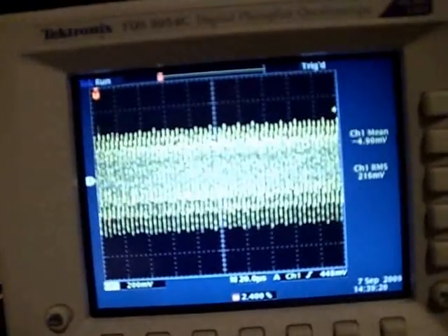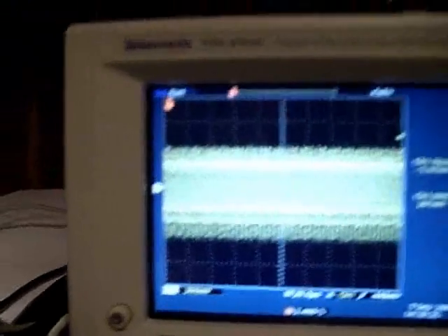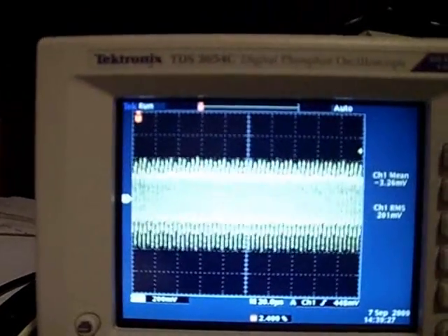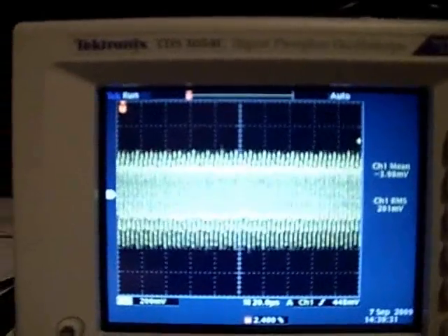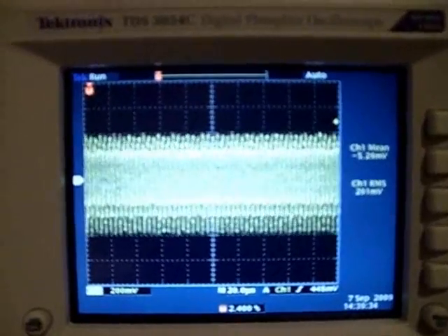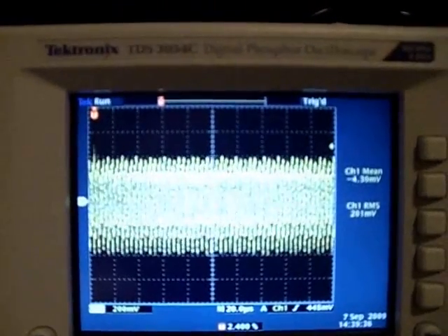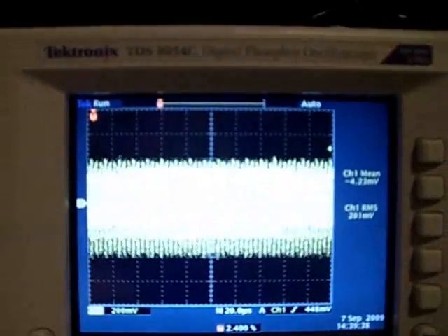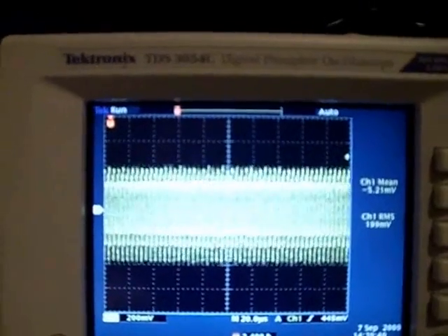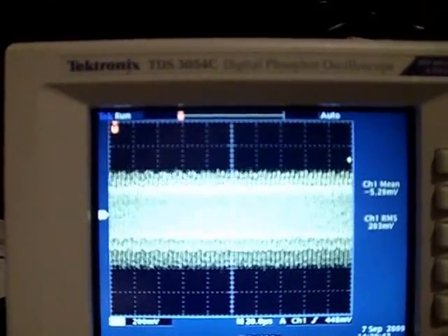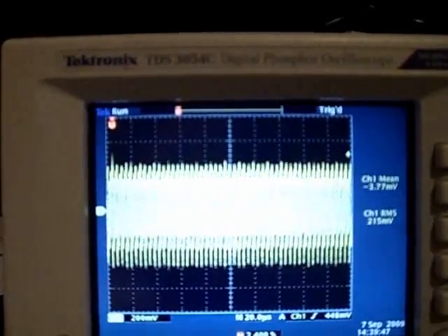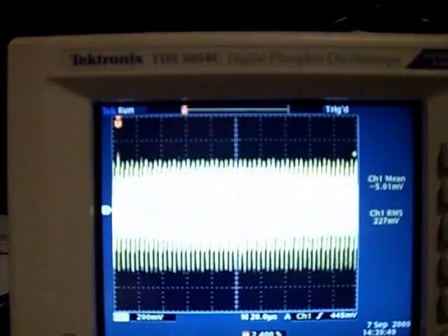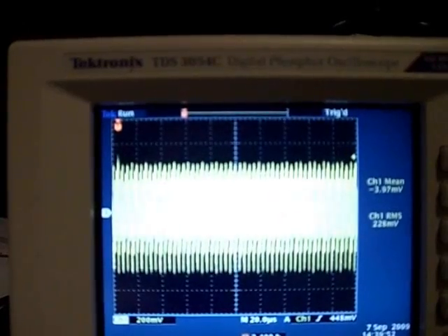Okay, and right now I'm at maximum resistance, which is about 5K ohms at the gate. And the waveform on the load is definitely more negative than positive. So I'm at maximum gate resistance. What I'm going to do is start reducing resistance. So I'm going in one direction, reducing resistance, reducing resistance, and you can see the amplitude is climbing.